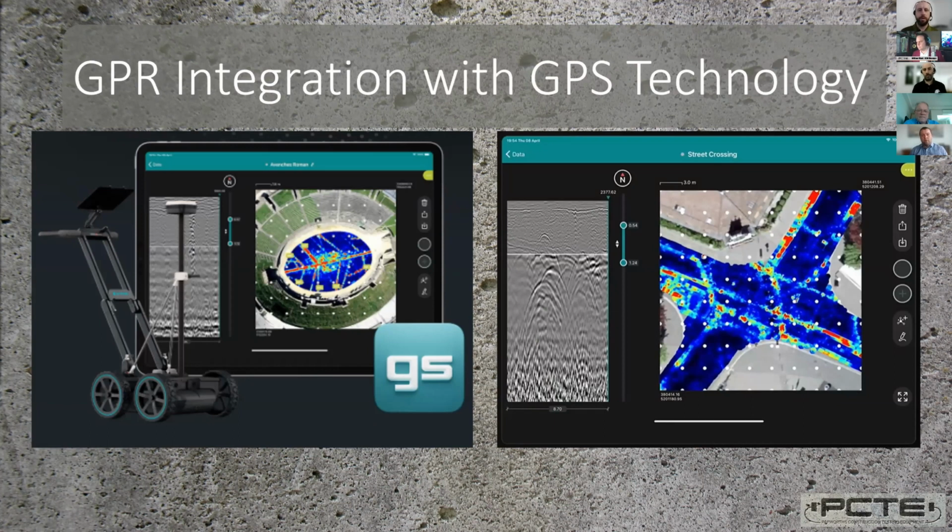All right, I don't want to spend too much time here because this is a large part of the presentation later, but currently, if we were to prepare imagery like this for a customer, we would need to put together what's called an area scan. So we'd need to be marking out a large grid, maybe 5 by 5 or 10 by 10 meter, and we'd have to be collecting all the lines in that grid. But with the benefit of a very accurate GPS built into the GPR system, it can actually record the path of the GPR and where it goes.